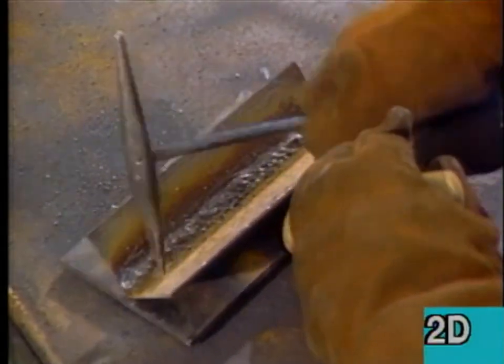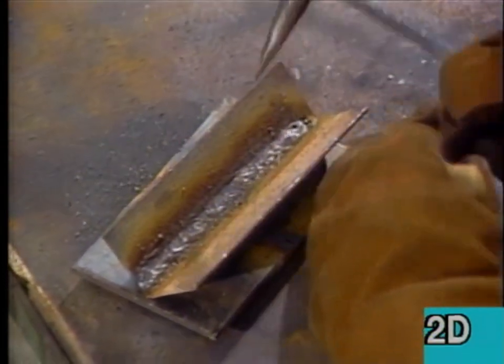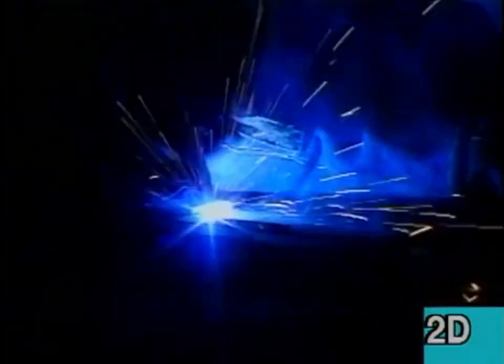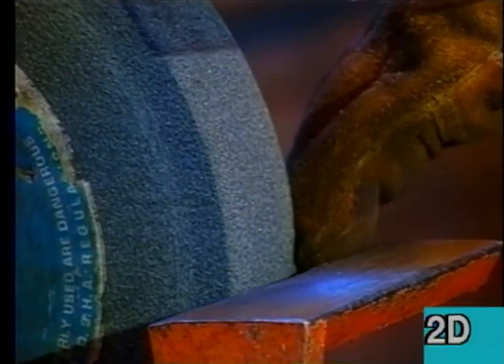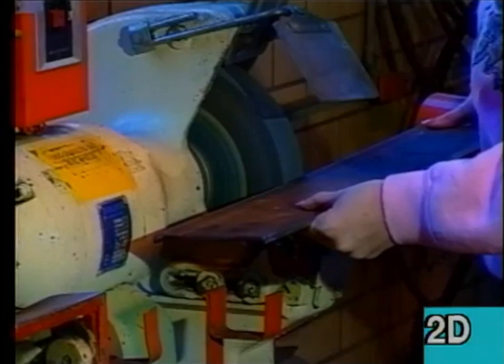There are times when gloves must be worn. When welding, gloves serve a twofold purpose. They help protect against electrical shock, but they also protect against burns as a result of slag or extreme heat. However, gloves should not be worn around moving machinery. Instead of protecting the wearer, gloves can get caught in the moving parts and drag the student into the equipment.